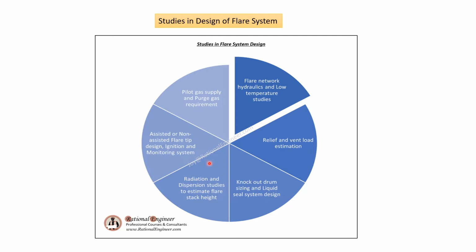radiation and dispersion studies to determine the flare stack height or to estimate the hazardous area classification, selection of the type of flare, whether it will be an elevated flare or a ground flare, assisted or non-assisted, the type of ignition and monitoring system, pilot gas supply to maintain the flame, and purge gas requirement to avoid oxygen ingress or backflow into the system. In this video, we will focus on the flare network hydraulic studies.